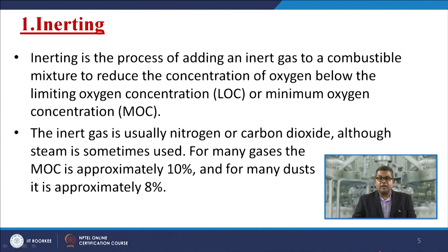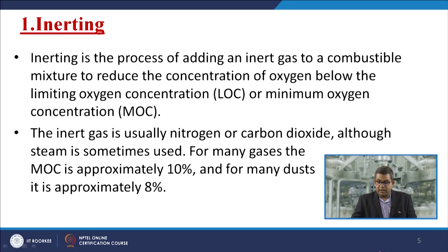Inerting is a process of adding an inert gas to a combustible mixture to reduce the concentration of oxygen below the limiting oxygen concentration or minimum oxygen concentration, so that the required stoichiometric demand is depleted and the flammable mixture does not catch fire. The inert gas is usually nitrogen or carbon dioxide, although steam is sometimes used but not commonly. For many gases, the MOC is approximately 10% and for many dusts it is approximately 8%.